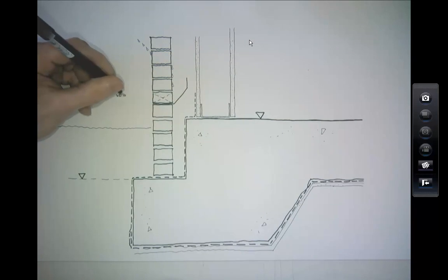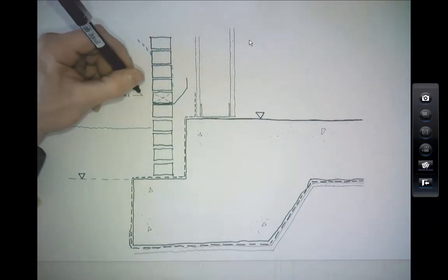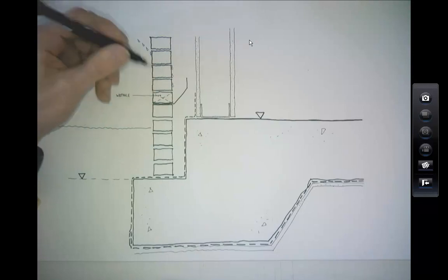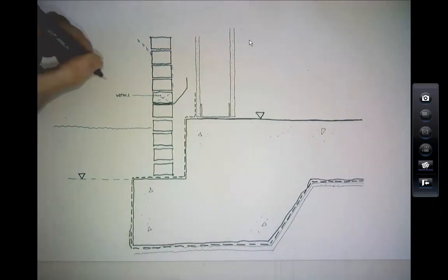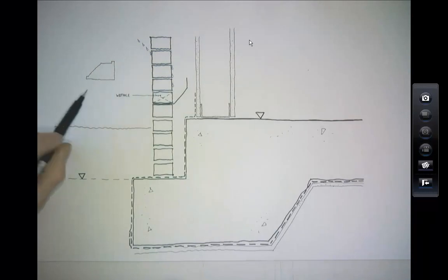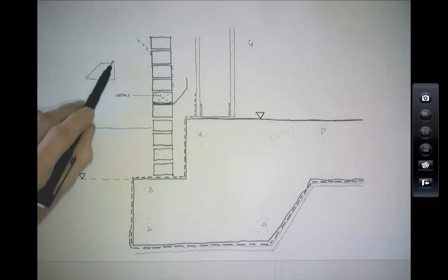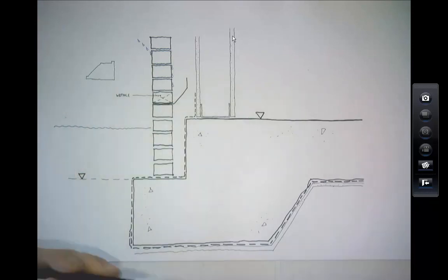And a weep hole, unfortunately I haven't got one, is just a little plastic insert that you put into the perp end, and it just lets the water dribble out. Okay? They look like, I'll draw one over here. They kind of look like that. So the water can get into it, dribble out, and it just drips out the front. Okay. So that's a weep hole.